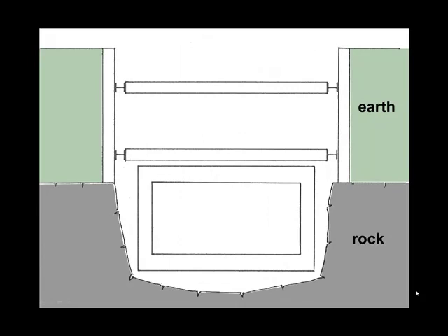The rock is removed by drilling and blasting, and naturally that's done with great care and great control. You certainly want to minimize the amount of rock excavation because it's very costly, but at the same time, if you don't over excavate, you will find tight spots, which means you have to return and somehow chip out those tight spots to provide enough space for your structure.